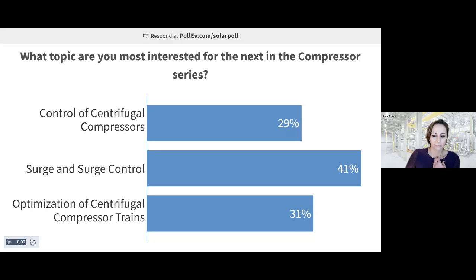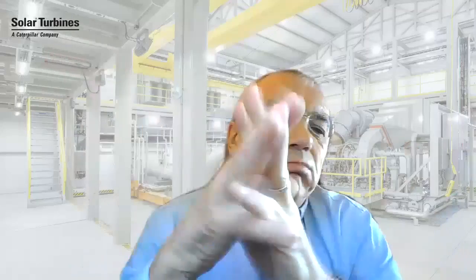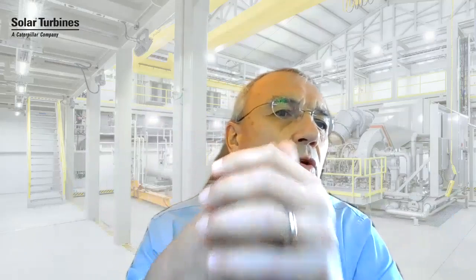Well, the intent of intercooling is twofold. One is you try to keep the temperature of your gas typically below about 350 degrees Fahrenheit or so. This is not a hard and fast number, but that's typically used in the industry as the guideline. The other thing is that if you compress gas, and you can intercool the gas, the amount of power that you consume for the same purpose will go down significantly on high pressure ratio applications if you cool the gas.